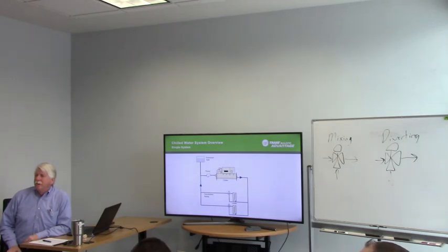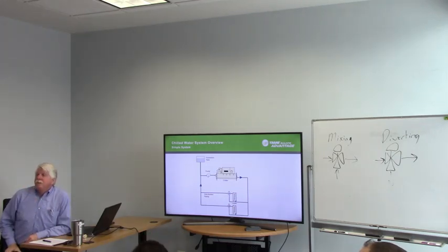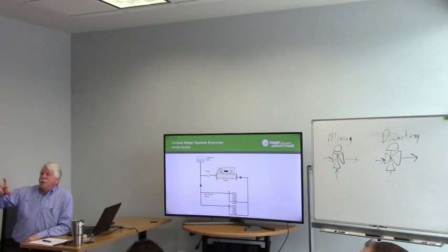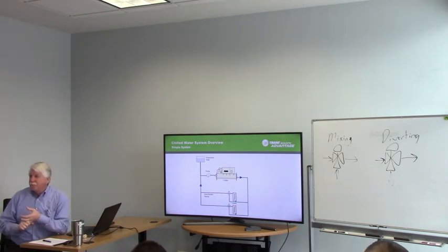So it's a pretty substantial savings when you drop a pound or two. Sure, yeah. So that relationship between flow and horsepower is what drives VAV systems and variable flow pumping systems. Okay?